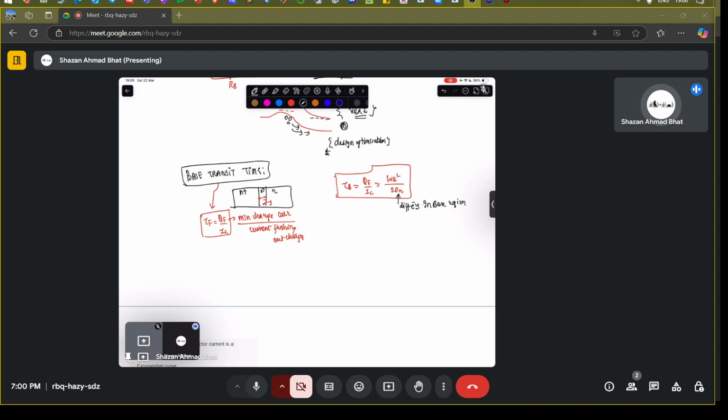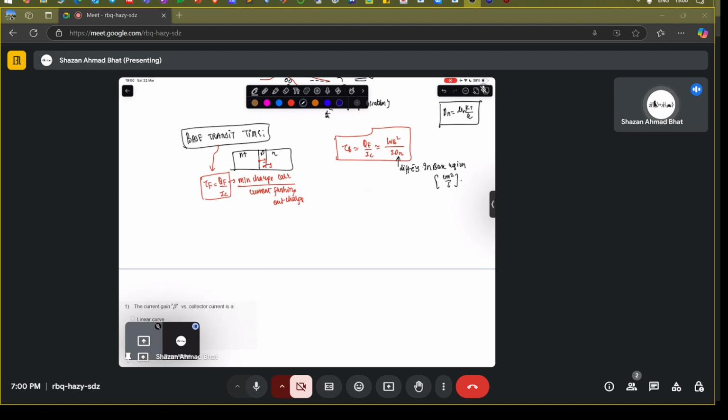Its unit is approximately centimeter square per second. So that's the diffusion constant of the electrons. And you might know that the diffusion constant is approximately mobility times kT over Q, the mobility of electrons. This is from Einstein's relationship. And now, because the base emitter junction is forward biased, you have different capacitances. You have a forward bias capacitance, which is the diffusion capacitance.